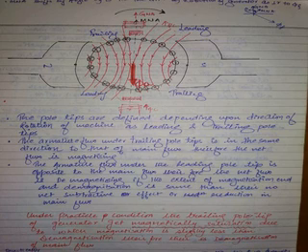Then is there any demagnetization? Yes. So only 1.9 Webers is flowing like this, right? So there is a demagnetization. Why is this demagnetization coming into the picture? Means saturation. You know, when the poles get saturated, once they are under saturation condition, they are reluctant to increase, but decrease has no problem. For example, when you are saturated, if I want to continue the class, definitely you will be reluctant.